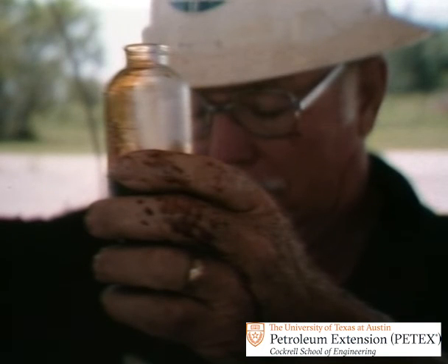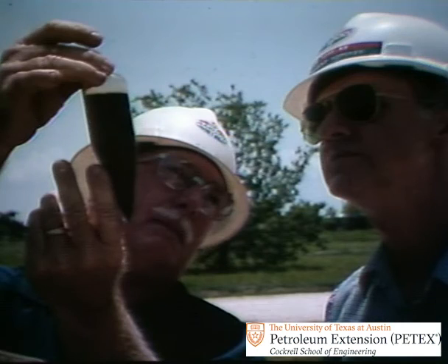If possible, draw samples directly into the glassware in which tests are to be conducted. You can foul up even the best sampling system if you mishandle the sample. So, if you have to transfer the sample into another container, try to minimize the number of times you do it. Also, get the sample to the lab as soon as possible to minimize settling time. Further, the lab should have mixing facilities to duplicate the mixing system you use at the sampling site.